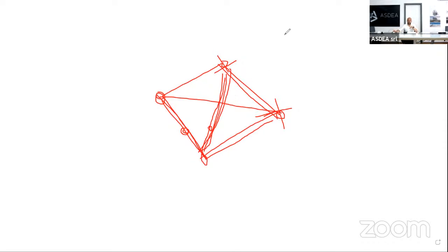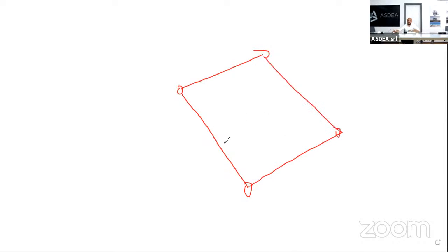In another case where you can see some sort of less accuracy is, for example, if you have a quadratic element, imagine like this, with a node here in the middle, okay? If this is a quadratic element and this node moves here, and this node, let's say, moves only here, you will see a quadratic displacement like this in reality, okay?